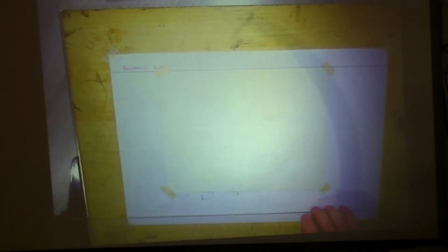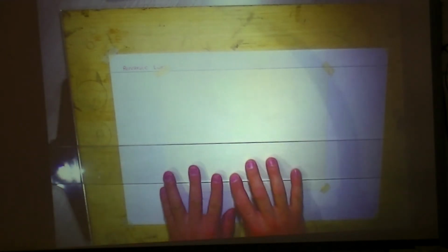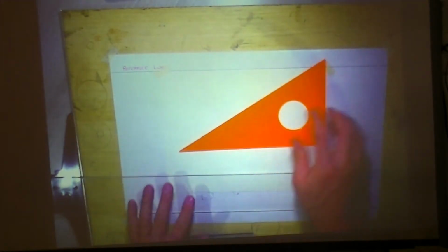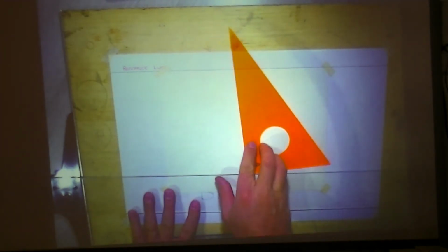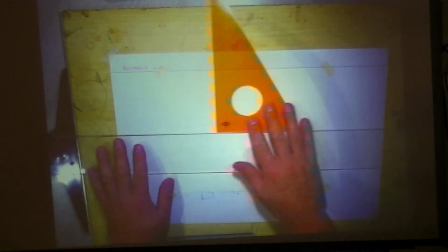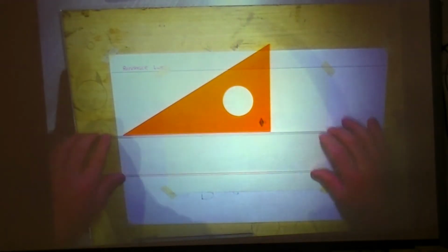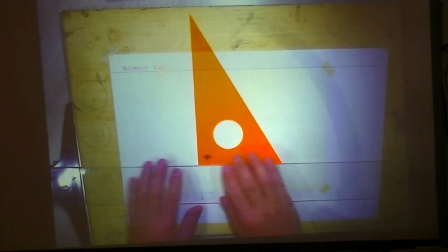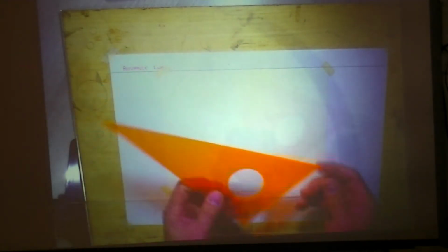But before we do that, we are going to go through, again, the drawing tools in order of the classroom assignment, which we just showed you a minute ago. So once you empty all the tools out of your drawing packet, you'll notice that there are 2 triangles, and they're both a little bit different, both equaling 180 degrees, of course. And there's a few different ways you could orient those triangles on the T-square to create different angles. This one happens to be the 30 degree, the 60 degree, and the 90 degree.